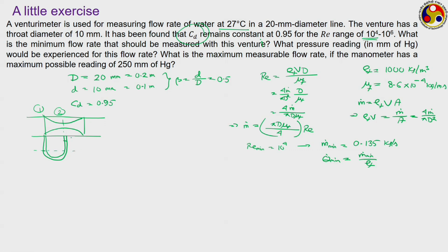If we see from there, in this particular portion we have a manometric fluid column of height h. Here we suppose have only the working fluid, which is water, with a column height of capital H. Then on the other arm, we have something left of height capital H minus small h of the same water. So, if we write a pressure balance along this dotted line now, then what can we write? On one side we can write P1 plus rho f g capital H, on the other side we can write P2 plus a manometric fluid column of height small h.